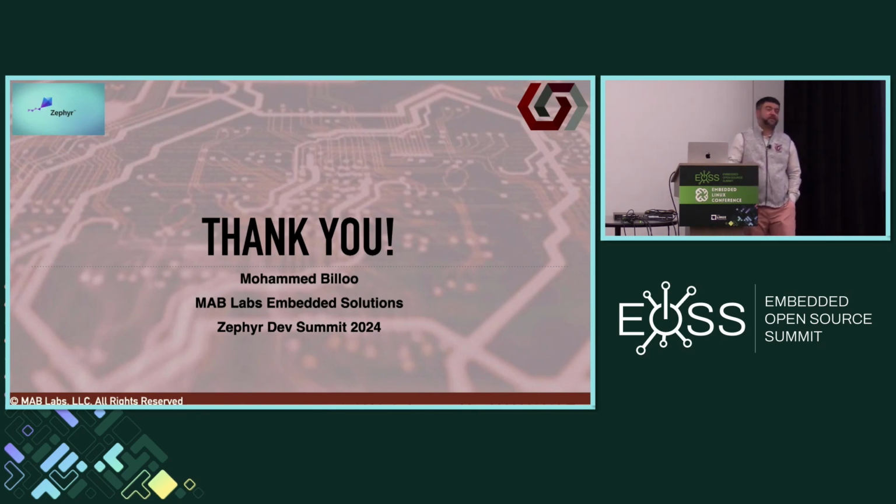Yeah, and just out of curiosity, where do you see that being valuable? So we're looking at robotics. The idea is that Linux is quality managed from a safety critical perspective, so that can die, that can reset, that can crash. And then the control loop is running on the Zephyr side. Especially that robot, it will trip over. If you're going to use Linux, if you have Zephyr, you have uptime, it shouldn't fall over. You just have power and you can run your safety critical or control loops. Got it. Well, yeah, cool.